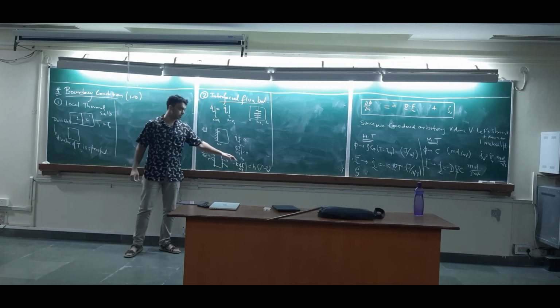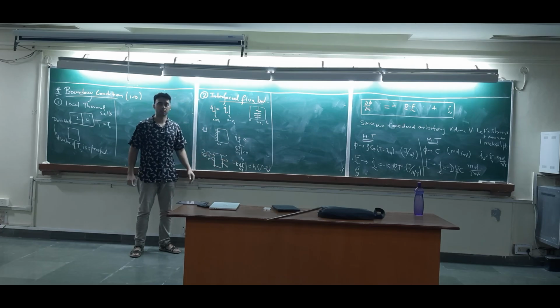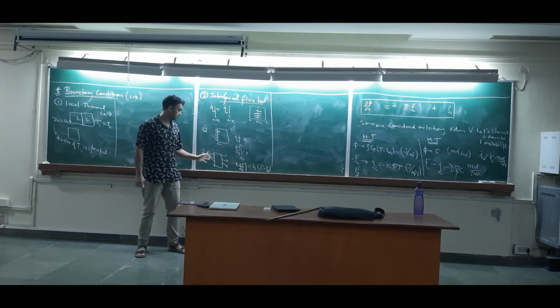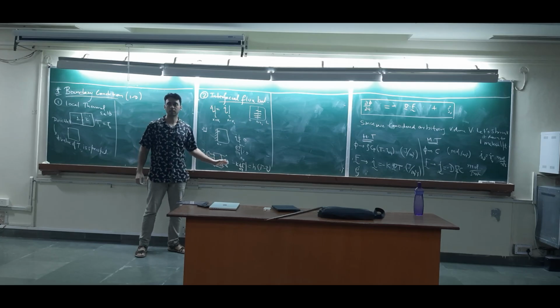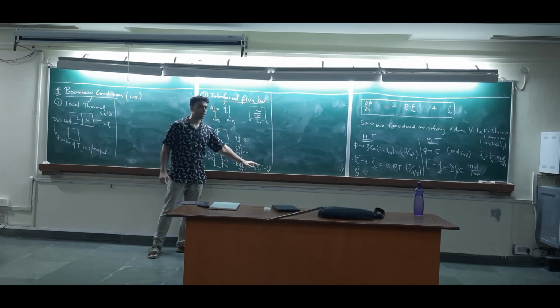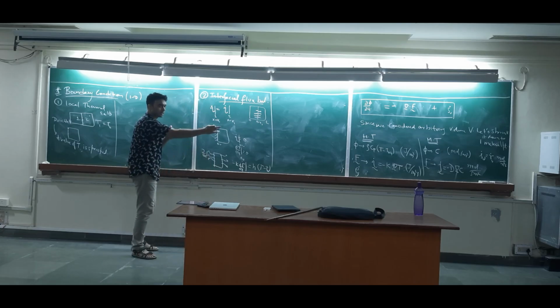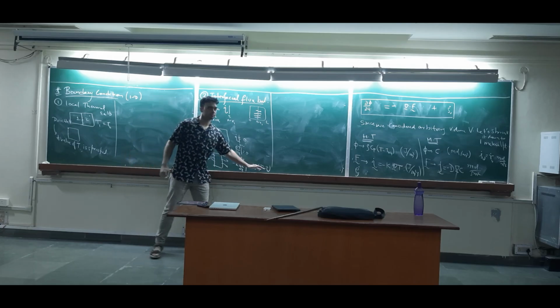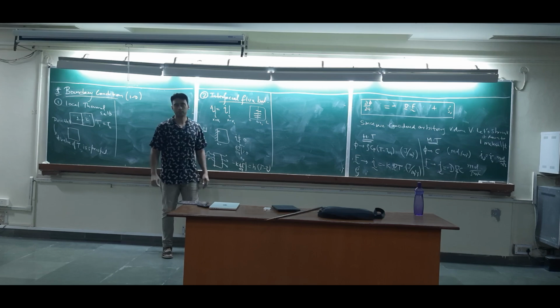But there's a catch here. This is usually, when I teach UG heat transfer, they make this mistake. They apply this condition here also and here as well. But you have to flip it. So a good way to remember this is that it's H into T lower coordinate minus higher coordinate, because your X is in this direction. So always take it like this. Lower minus higher coordinate.